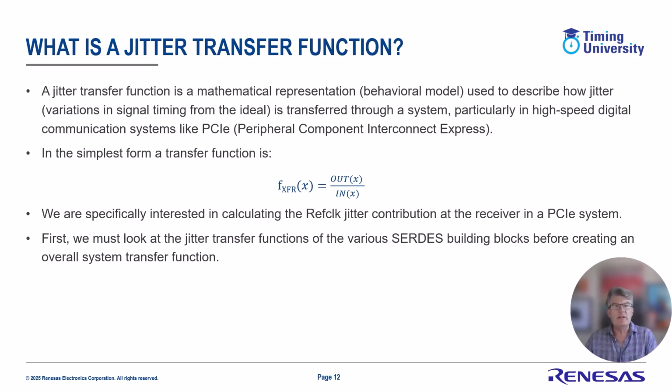We will need to understand what a jitter transfer function is, though. A jitter transfer function is a behavioral model, which means it's a mathematical representation, and it's used to describe how jitter is transferred through a system, particularly high-speed serial interfaces like PCI Express.